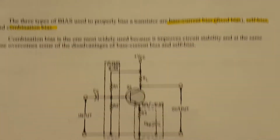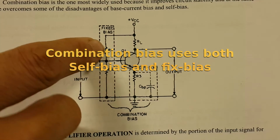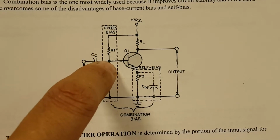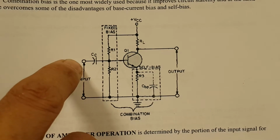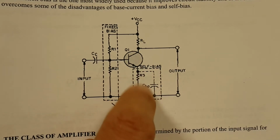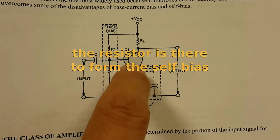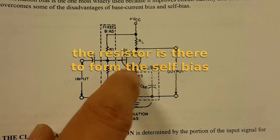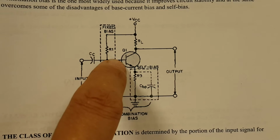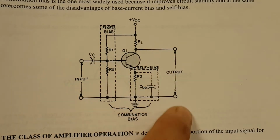A combination bias is where you take a fixed bias, and what's fixed is this over here, because we got a voltage divider, which is R1 and R2, and they are fixing the amount of voltage that is over here, and that only changes based on whatever sine wave the input brings. To stabilize it, there is this resistor over here that improves the stability of the current flow between the emitter and the base, and therefore by accomplishing stability between these two, you are accomplishing a good stability between the emitter and the collector, which is what's going to the output.